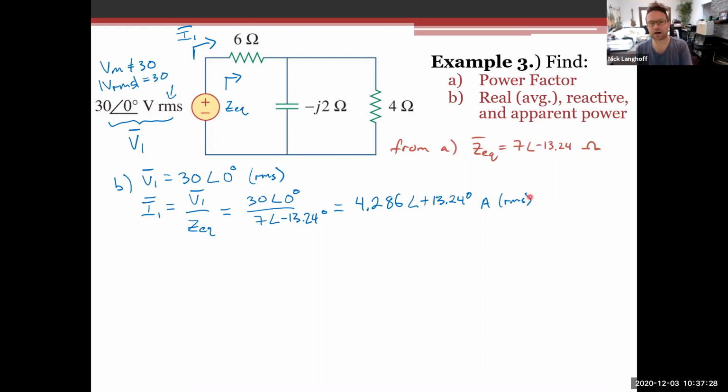And so now we want to go ahead and calculate the apparent power. And once we know the apparent power, in fact, I take that back. Let's go ahead and calculate the complex power, because the complex power will tell us, once we know its form in mag phase or polar form, and we know it in rectangular form, everything we need to know. It'll tell us the real power. When we see it in mag phase form, it'll tell us the apparent power and the phase angle, and then we'll extract the real and reactive powers from it in rectangular form.